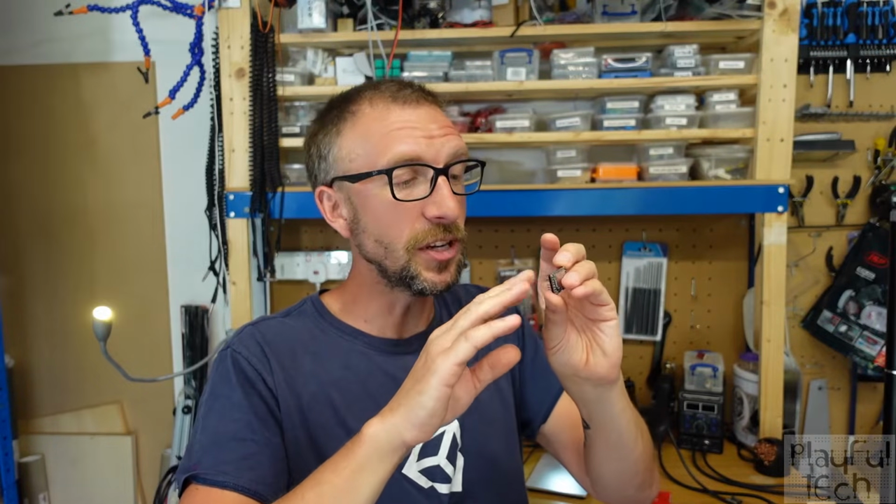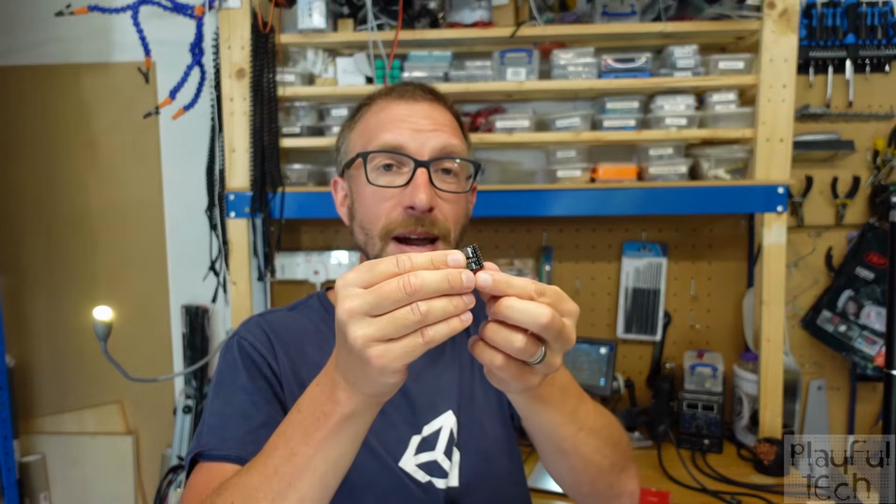The board has got stereo DAC output and even has a small onboard amplifier chip, so you can connect a small speaker directly to it. But it should be said that these are not quite plug and play devices. Even though you'll find examples on the internet where people just plug in 5-volt power or wire directly to the GPIO pins on an Arduino, that's not correct.